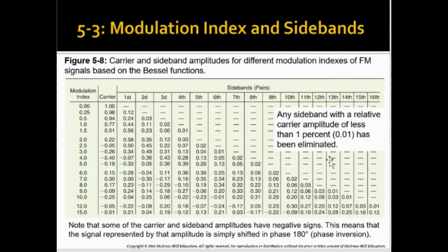If the amplitude is too small, there is not much power and it is not very significant in your demodulation. So you can reduce your bandwidth to collect only those sidebands which carry the highest power.